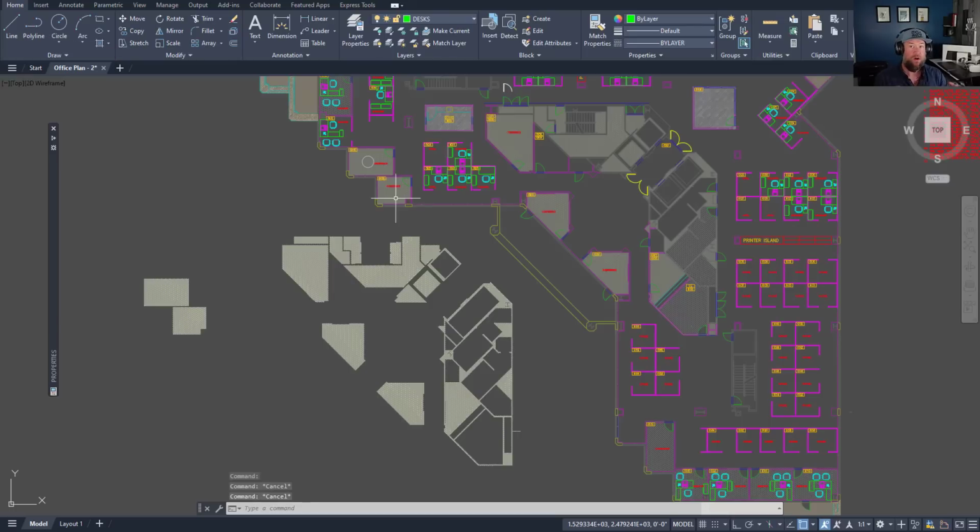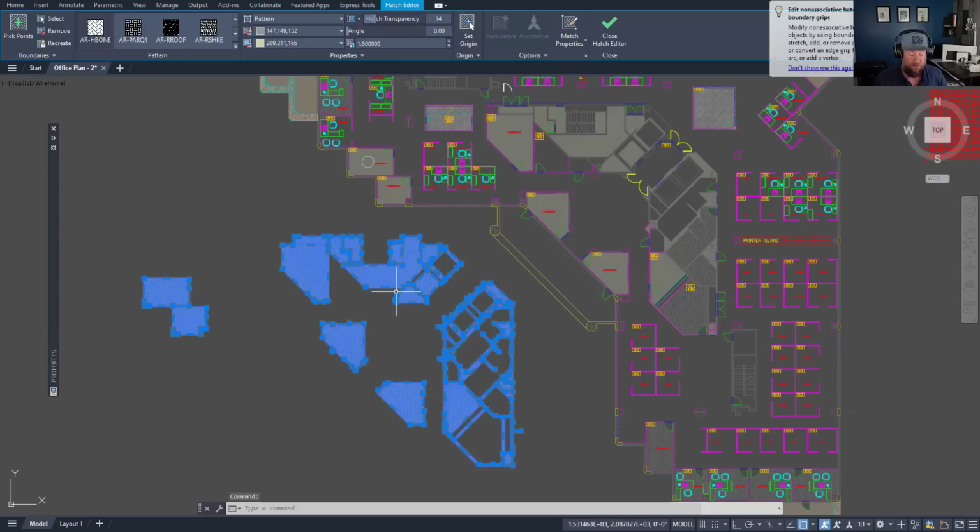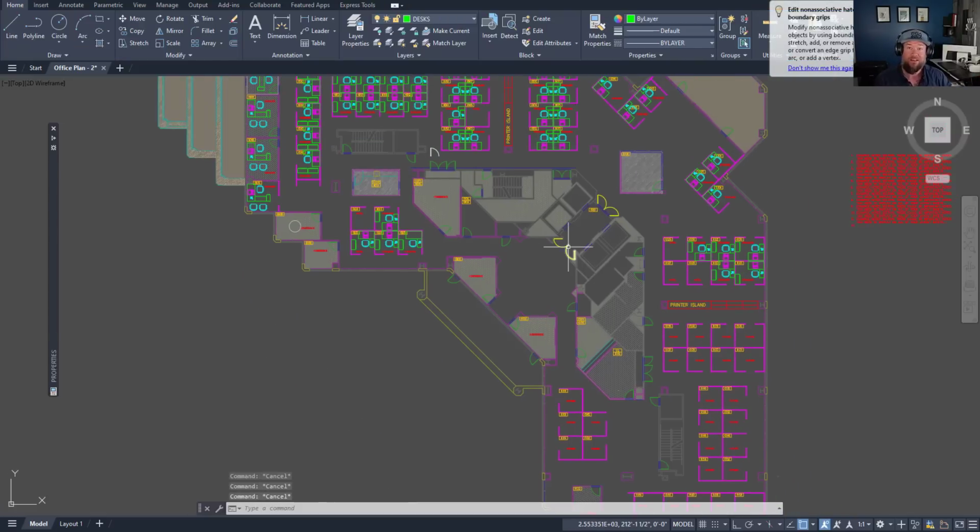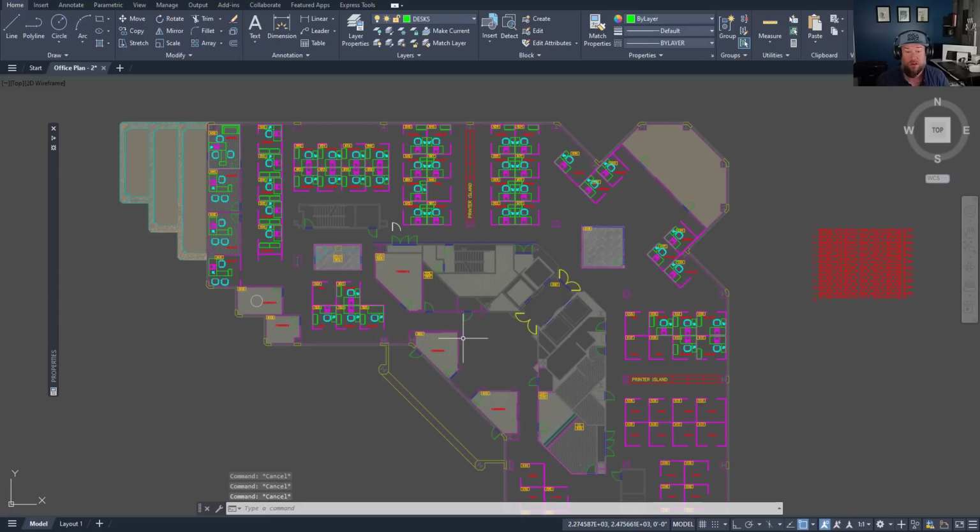So if you want to layer in and bring in some XREFs, copy a few objects in, and then detach or disconnect that XREF, you can still have that object or those line works and blocks in your drawing without having to open and copy objects back and forth. This one is super useful and a huge time saver for those drawings where you're using a lot of XREFs and just need to grab, say, a simple little manhole block or a piece of the wall or a door. And moving on, we're going to check out the oops command.